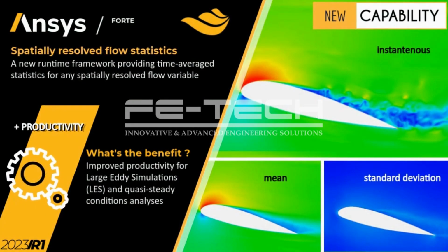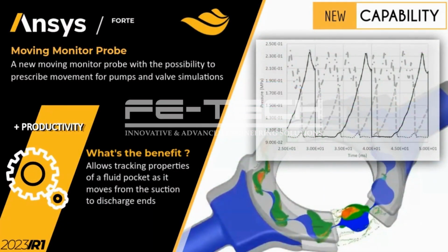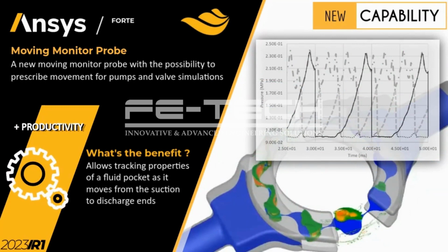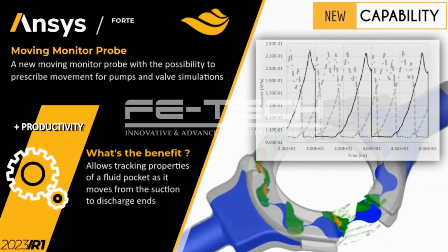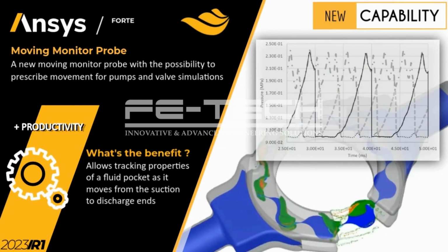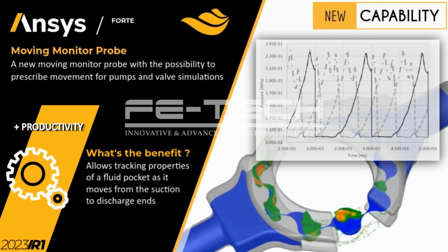A new runtime framework providing time-averaged statistics for any spatially resolved flow variable improves productivity for large eddy simulations and quasi-steady condition analysis. And the new moving monitor probe with prescribed movement allows tracking properties of a fluid pocket as it moves from the suction to discharge ends in pump and compressor simulations.